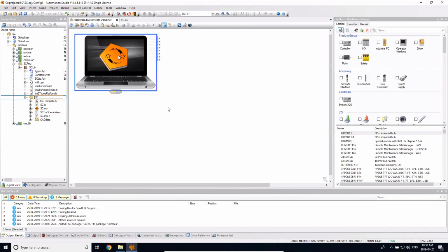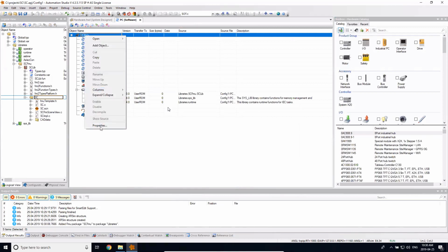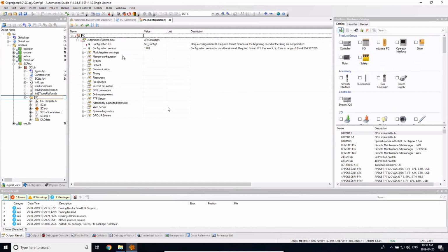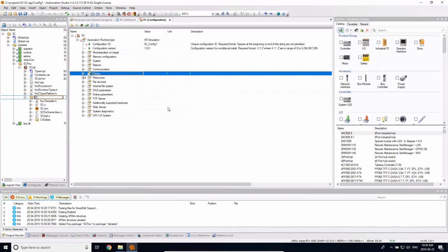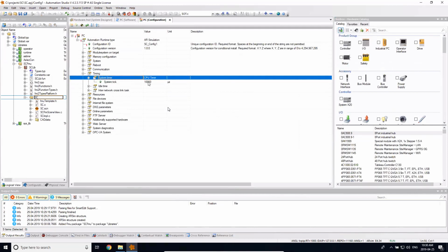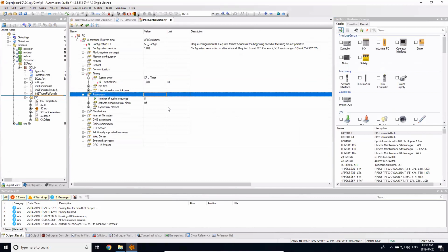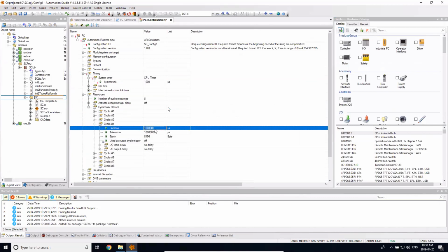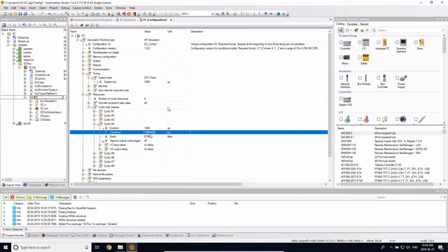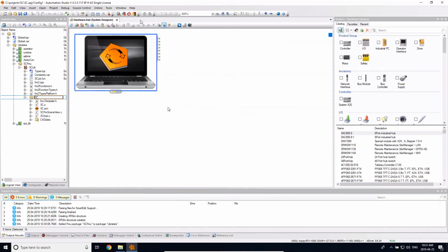And just before I forget, I'm going to update some of my system properties. This is just so that the communication between the FMU I generated and the system and how it's running are going to sync up nicely. So this time that I'm using is actually just the communication step size that I would have defined in the B&R FMU Generation tool from MapleSim, and this is the task class time. So with this set up, I'll save these configurations, close these tabs.